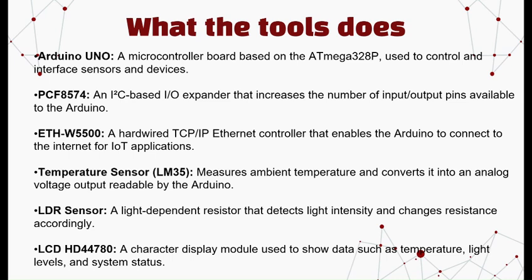What does each tool do? An Arduino Uno, a microcontroller board based on the ATmega328P, is used to control and interface sensors and devices. PCF8574, an I2C based input-output expander that increases the number of input and output pins available to the Arduino.